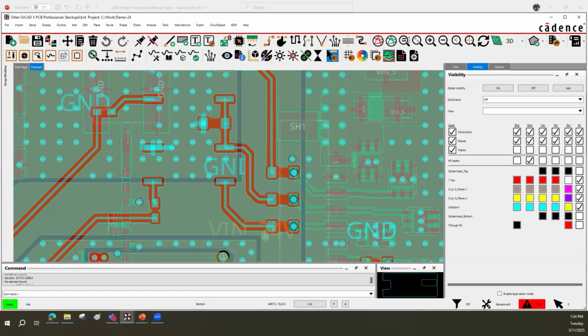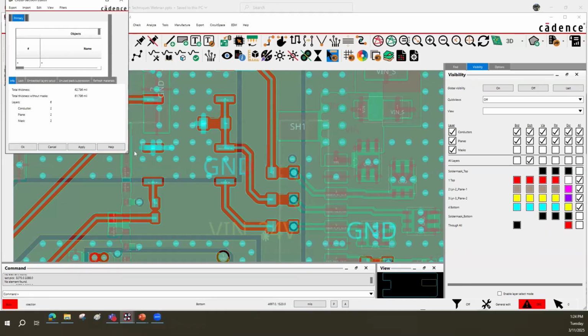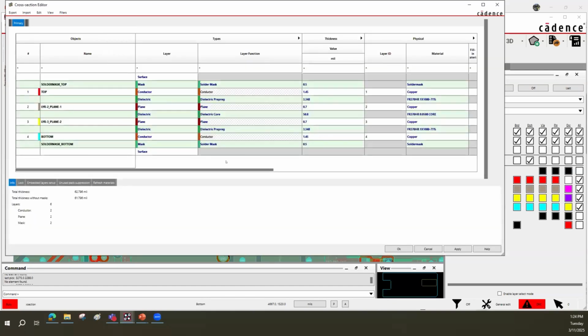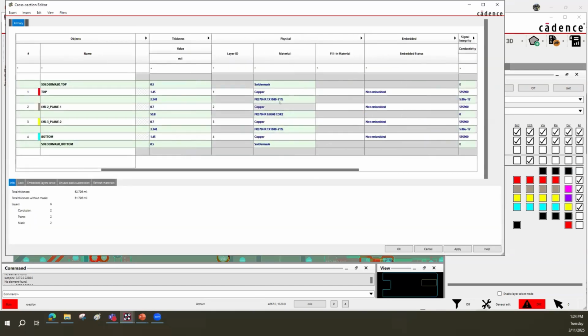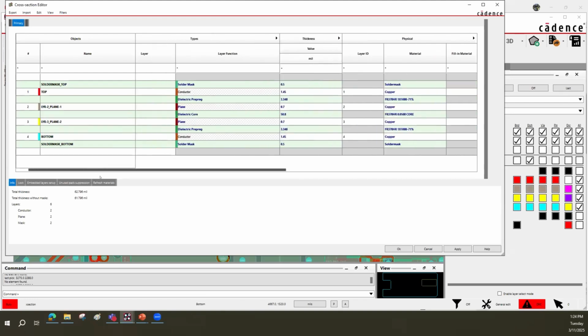Now I have a new Stackup, and I can go into my Stackup here. Let's expand that out. And I can see that the material has changed from what I had. They're using the FR 370HR material where I had a Rogers material in there. And notice that their cores are different too. Their cores were the two planes as a core, where mine wasn't. So the core had actually changed from what I had first depicted, and pre-preg materials are now on the outer.